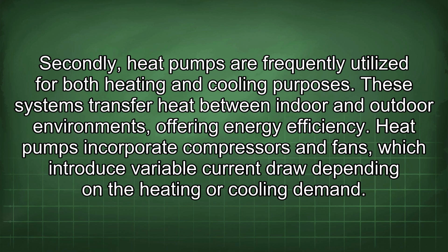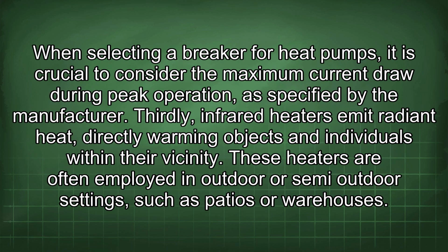Secondly, heat pumps are frequently utilized for both heating and cooling purposes. These systems transfer heat between indoor and outdoor environments, offering energy efficiency. Heat pumps incorporate compressors and fans, which introduce variable current draw depending on the heating or cooling demand. When selecting a breaker for heat pumps, it is crucial to consider the maximum current draw during peak operation as specified by the manufacturer. Thirdly, infrared heaters emit radiant heat, directly warming objects and individuals within their vicinity.